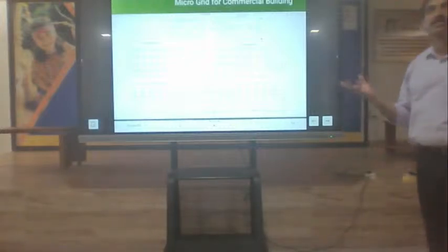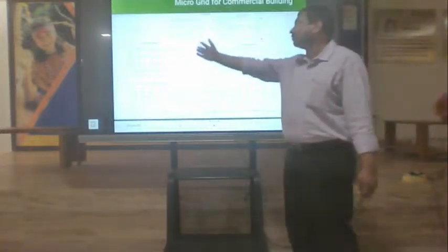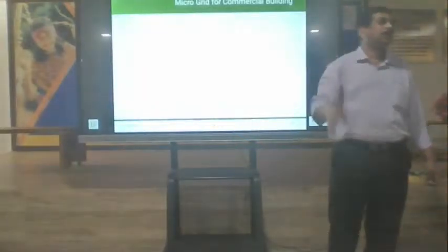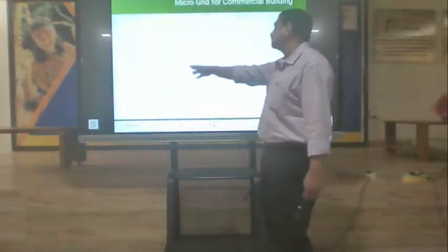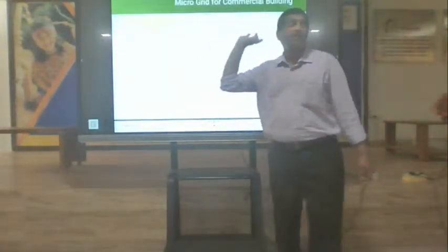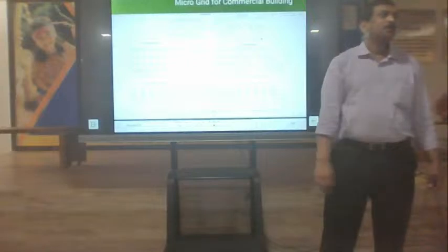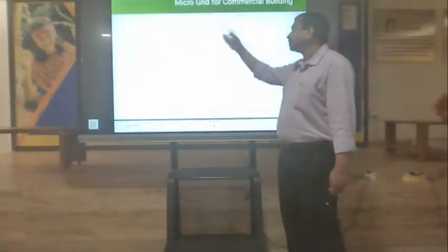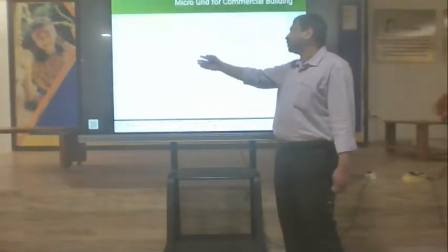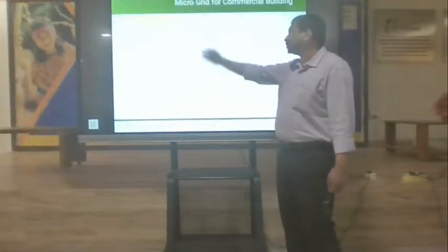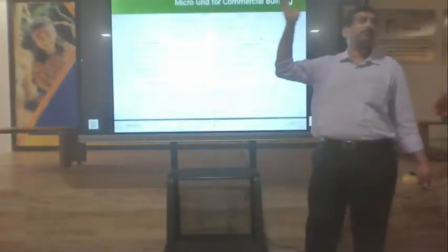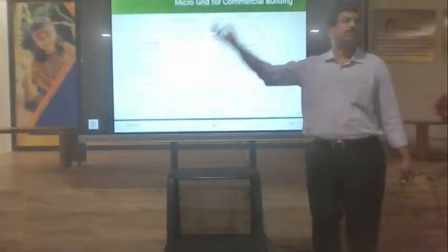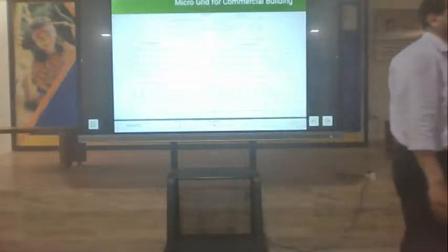Because of the natural potential difference, when the potential difference of the rectifier is higher than the solar, the load is naturally drawn from the rectifier. The rectifier is a strong source, having more power. Whenever I load, the solar voltage will fall below the rectifier voltage. So naturally the rectifier is at a higher potential than the solar, so most of the time the load goes to the rectifier and the solar is getting unused.